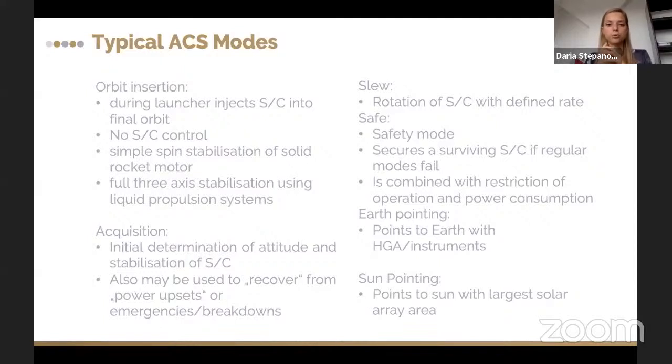In the slew mode, rotation of the spacecraft is defined with the safe regime, and it's combined with the restrictions of operation and power consumption. In Earth pointing mode, the satellite points its instruments to Earth, and in the sun pointing mode, it points to the sun with the largest solar area.